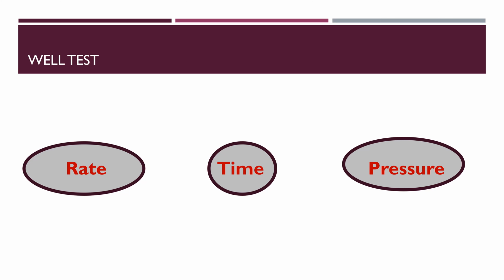We have downhole gauges that are highly sensitive, that take note of every action that you take. Why? Later on, when you are moving onward to the step of well test interpretation, if you have pressure anomalies, if you have something that is difficult for you to justify or interpret, you have to find the report and check exactly what happened at that time.